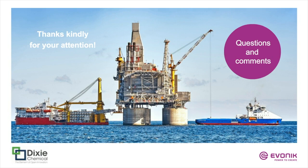I mean, the role of the dianhydride and the monoanhydride goes to the extent of cross-linking of the epoxy resin itself. As the data showed, you can really affect the properties of the finished product by the ratio of monoanhydride to dianhydride. The main effect of using BTDA as a thermal curative for these systems is that it's tetrafunctional as opposed to difunctional in the monoanhydride, which imparts much greater cross-linking density, and therefore really drives up the thermal properties and compressive properties of the material.